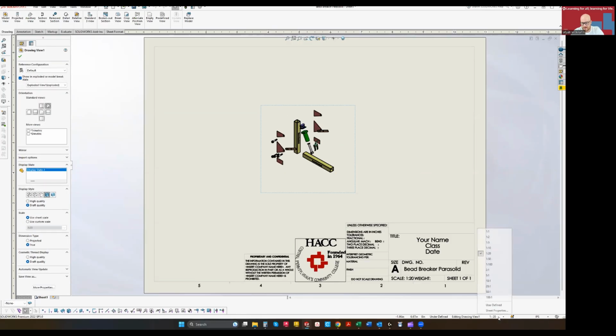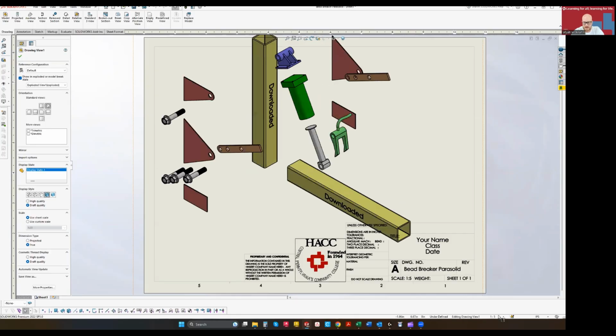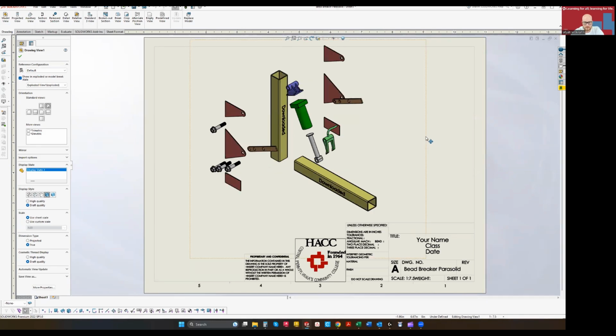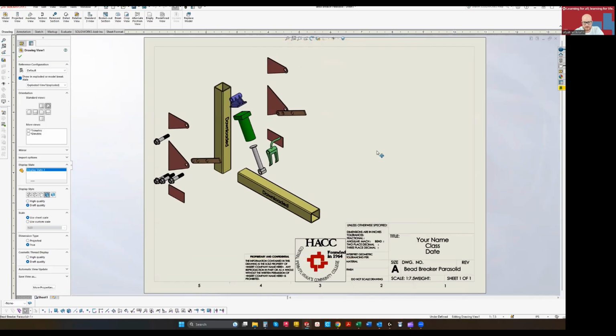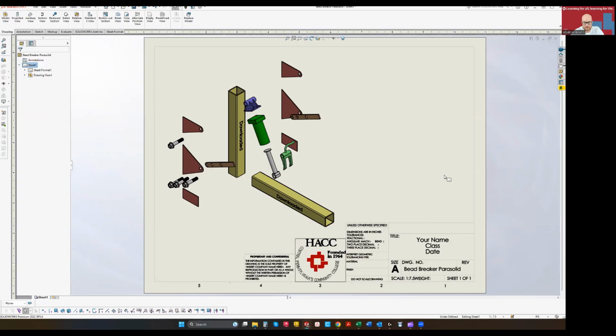So we're going to take that. Let's go ahead and make this maybe 1 to 10, see what that looks like. Still maybe a little smaller than I would like. Try 1 to 5. I think this is going to be too big. So let's do a custom sheet scale, user defined. And maybe make this 7.5. That'll probably work. Sticking off the top of the page a little bit. So let's just kind of bring it in, something like that. There we go. I'm not going to worry that this is kind of off the edge here.